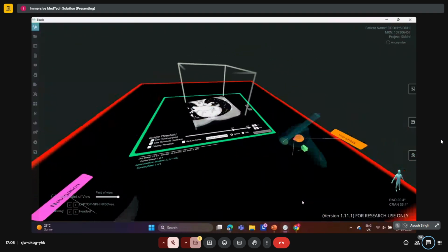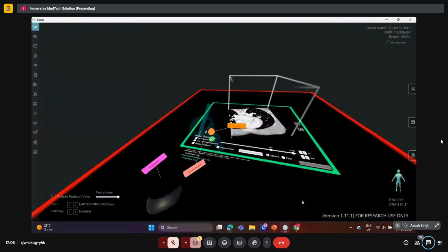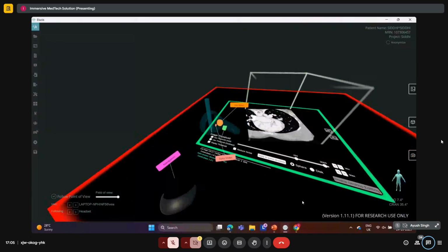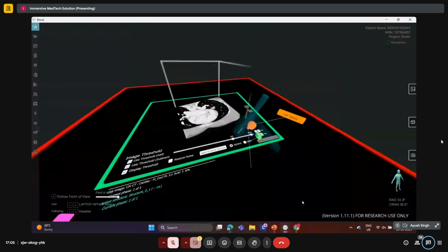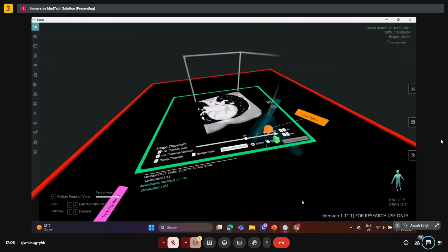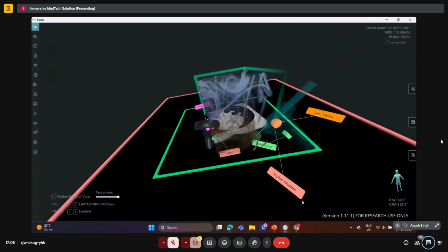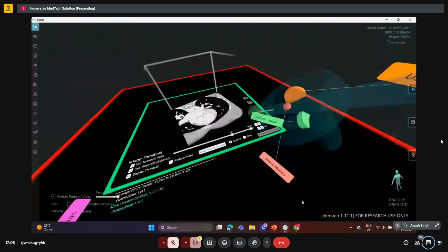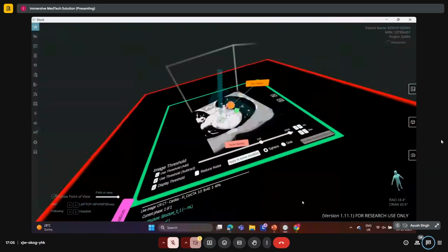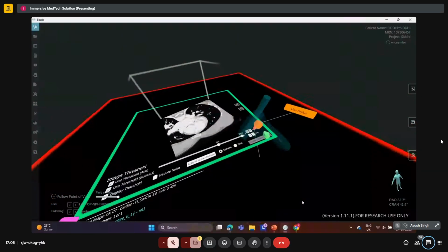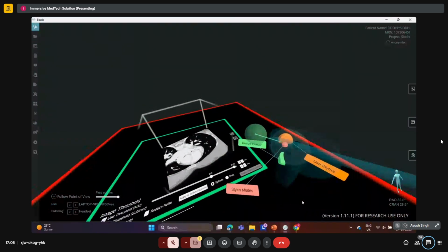Here now, what I was showing in the picture in the PPT earlier, is the image threshold window that we are having. Here is the use threshold add and use threshold subtract. Then here is the display threshold. What this display threshold does is it will highlight the particular region. So the pink region that you would be seeing might not be that clear in the video, but I can pretty clearly see the particular pink region over here that is getting highlighted. We can select a threshold range, and once that is done, we can start doing the sculpting.